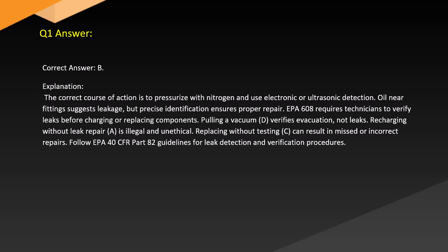Answer. Correct answer: B. Explanation. The correct course of action is to pressurize with nitrogen and use electronic or ultrasonic detection. Oil near fittings suggests leakage, but precise identification ensures proper repair. EPA 608 requires technicians to verify leaks before charging or replacing components.